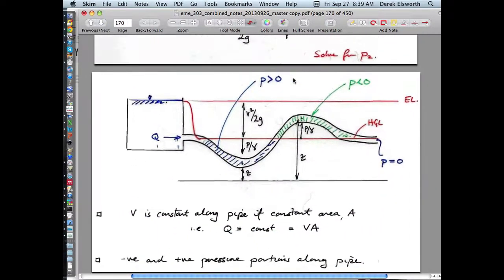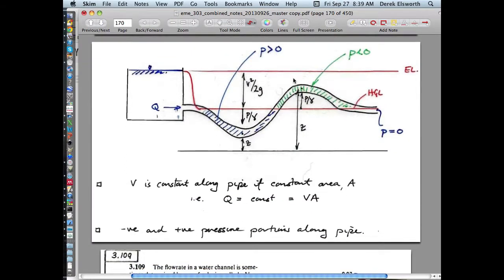So the other way to think about this actually relates to something that you saw a couple of nights ago, it's also related to the Venturi flume as well, is that you can make the same application to a pipe that goes along. The pipe has a constant diameter and goes between an upstream location and a downstream location. So you could write Bernoulli for this.